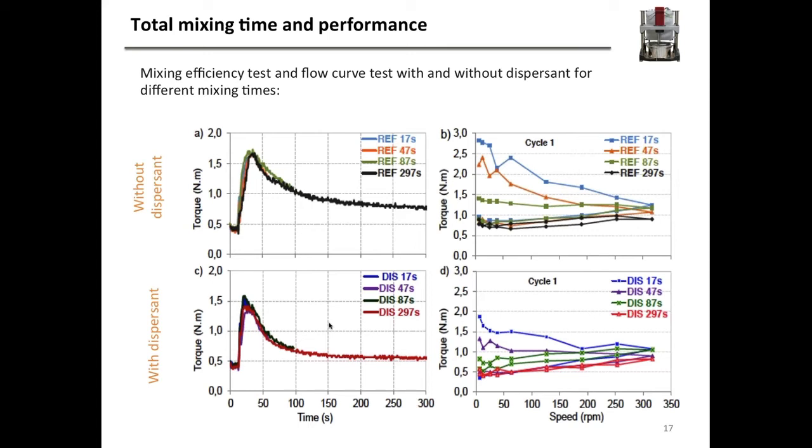What you would do, of course, as the next step, is compare two dispersants, and then compare dosages, and then make an educated decision on which dispersant to use based on its cost, how easy it is to get, how easy it is to use, and other criteria. It helps you make a very educated decision on what the best dispersant is. And the best dispersant might not be the best for all of your concrete mixtures. It depends on what else is in that mixture.